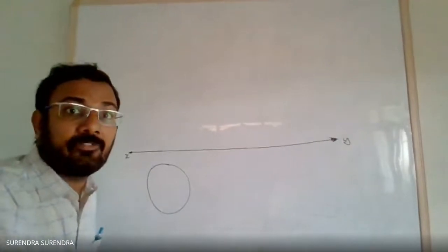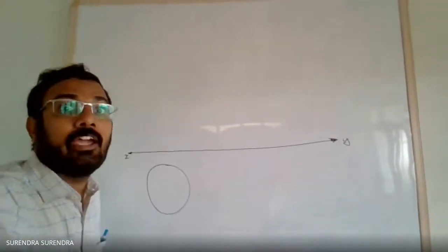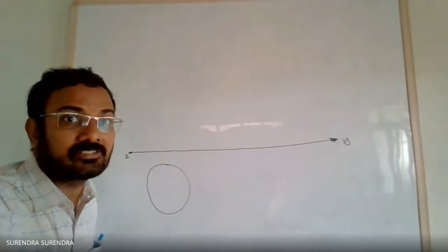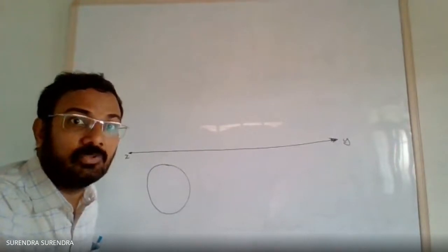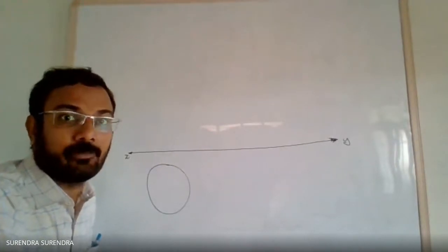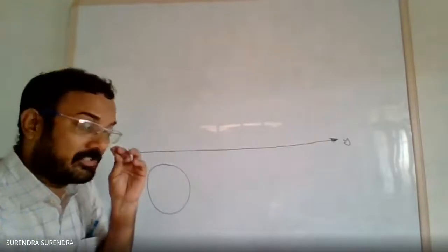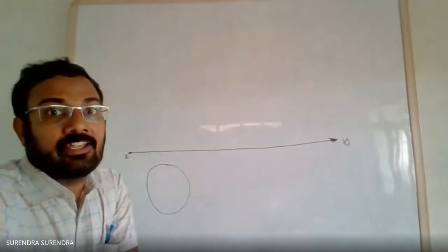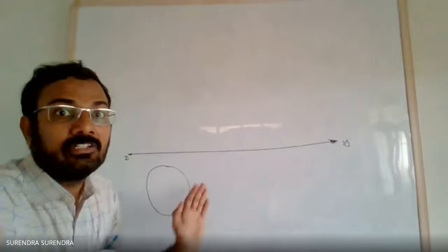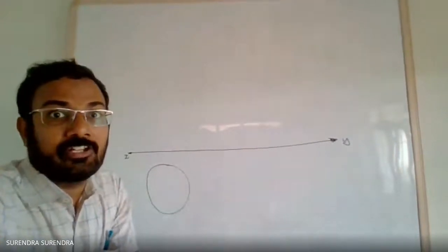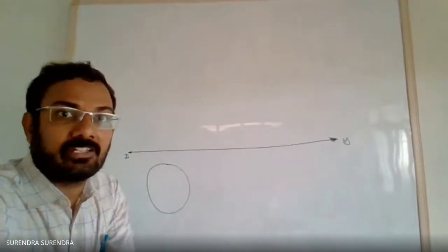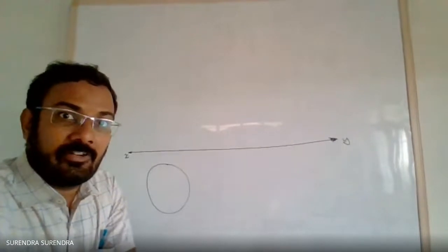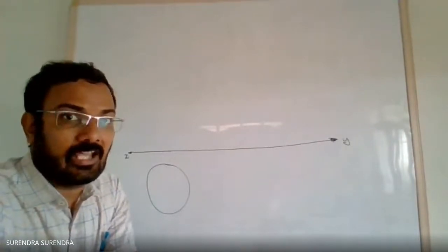Better divide this circle into 8 or 12 equal parts. If you divide it into 12 parts, you will get a more accurate shape in the next view. If you divide it into 8 parts, you will get a little less accurate shape, but dividing it into 12 takes time.